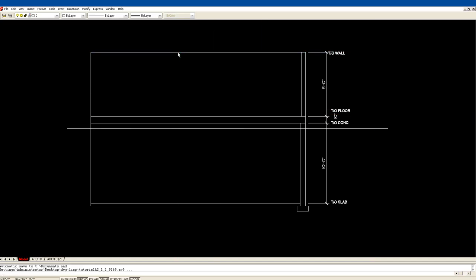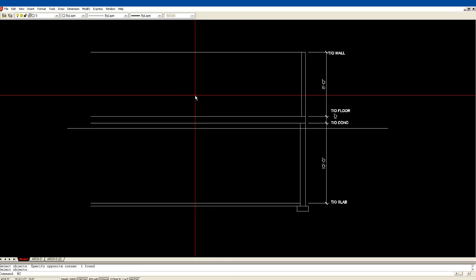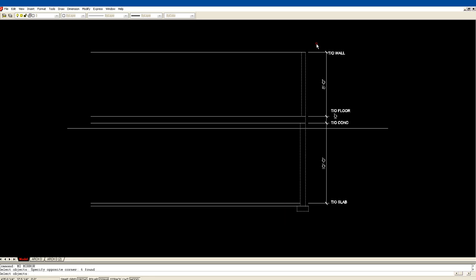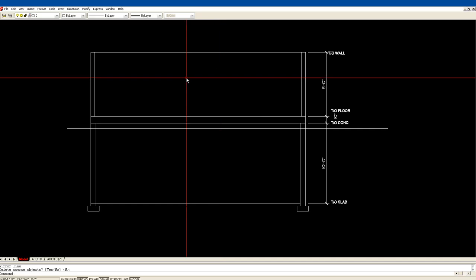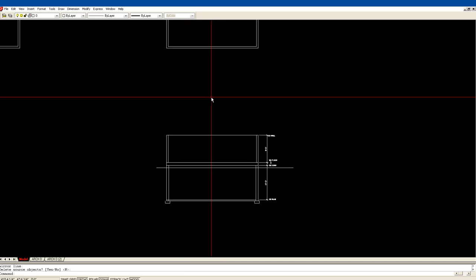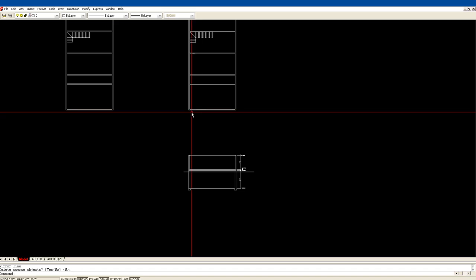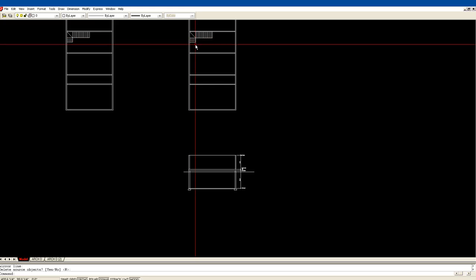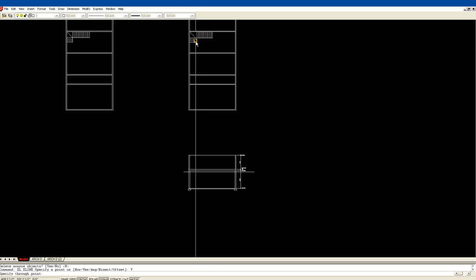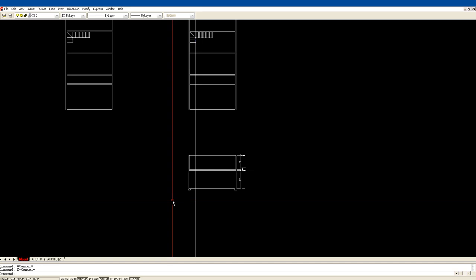Now, this line right here goes from side to side, so I can erase that one and I can just mirror all of this that we've drawn here. Right in the center there, enter. So really there's the 2 sides of the building. What we've done is a cross section, which looks sort of like an elevation. Here are our stairs, and so we can do an X line vertical just to the edge of those stairs. Okay, so that's 30 or 42 inches.